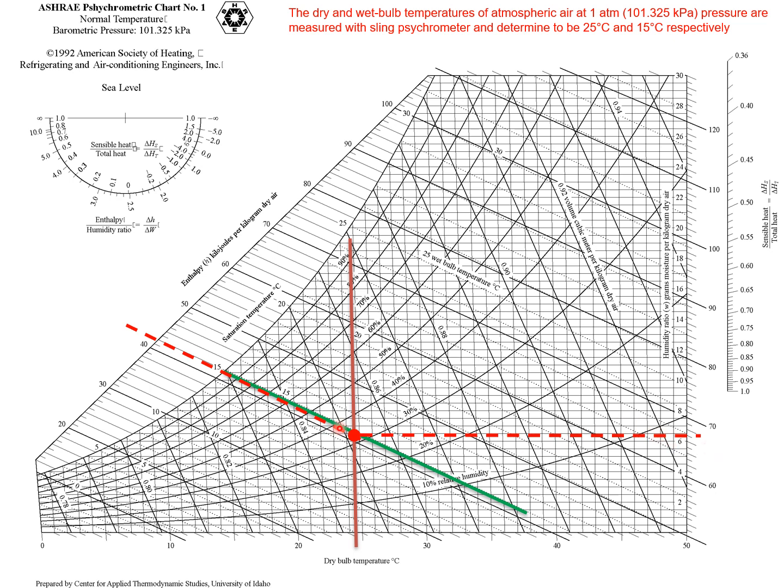So enthalpy, you draw a line which is parallel to these lines and it intersects to this point here. Based on the scale given, then you can find what is the enthalpy that you want.